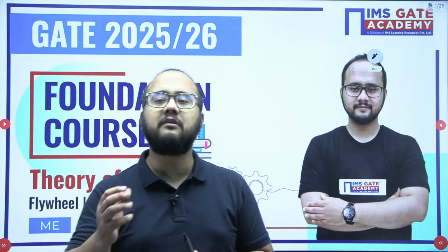But at the end what do we want? Uniformity in the power. So to get that uniformity we will be using this flywheel. If you don't use a flywheel, then there will be a fluctuation in the energy, and because of that fluctuation of speed will happen, and ultimately we have to suffer from those fluctuations of speed, because there will always be a jerk. So in order to avoid those scenarios, we have to use a flywheel here.